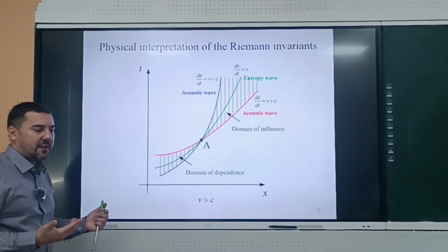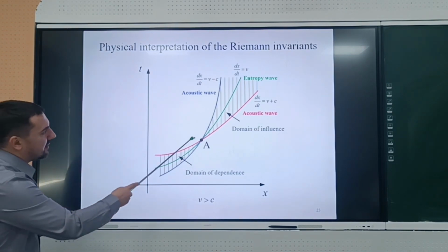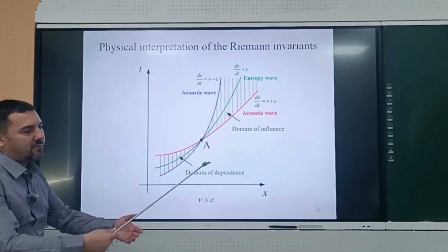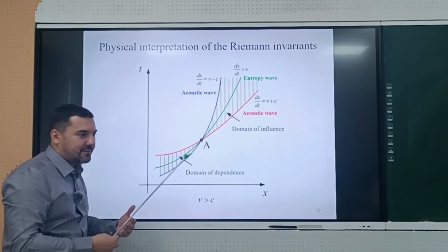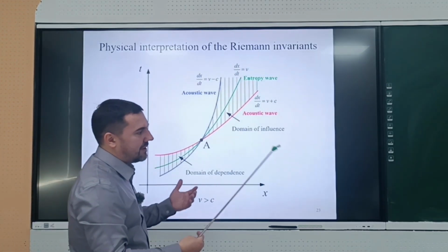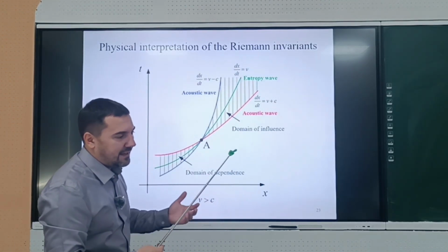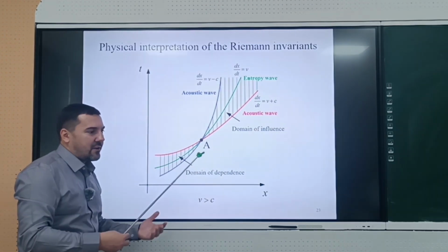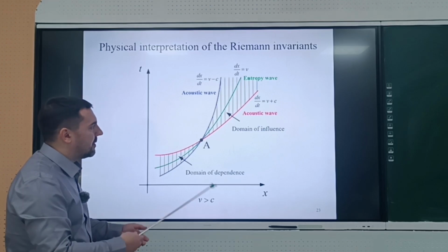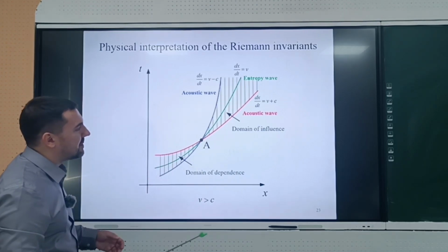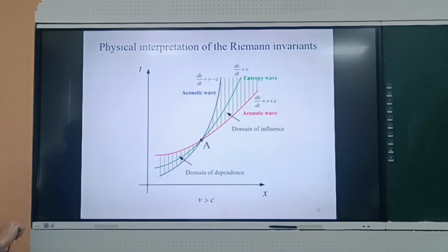But which conditions should you take? The problem is that for the subsonic case, the flow in your domain will affect your inflow boundary conditions. And so that's a problem. That is why people introduce a number of numerical representations for the same, from a physical point of view, boundary condition, because of this very complex mechanics of wave propagation in compressible media.